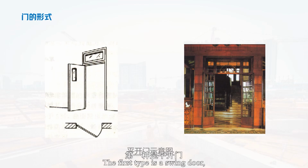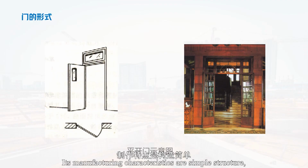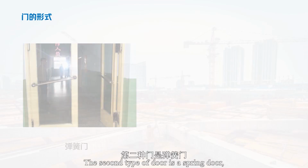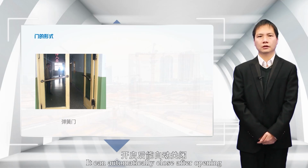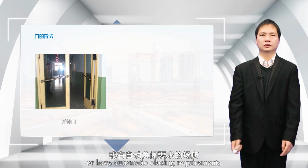The first type is a swing door, which opens horizontally and can be divided into single and double leaf, internal and external openings. Its manufacturing characteristics are simple structure, flexible opening, and easy installation and maintenance. The second type of door is a spring door, which is simple to make, flexible to open, and constructed with spring hinges or floor springs. It can automatically close after opening, and is suitable for places where people flow in frequently, or have automatic closing